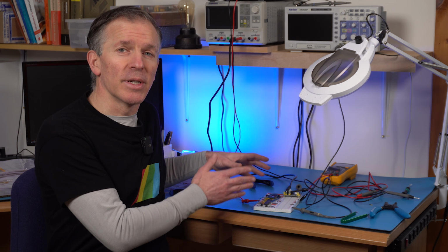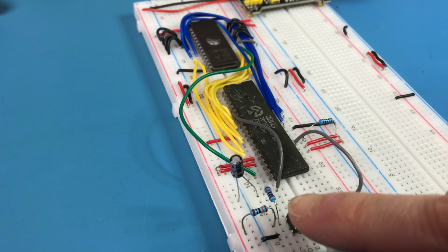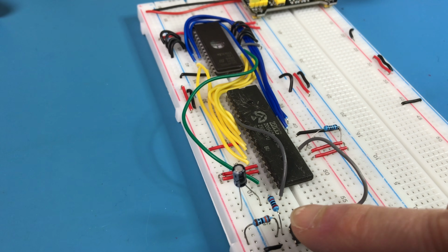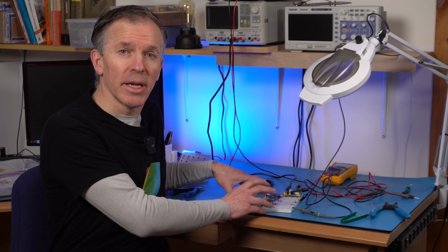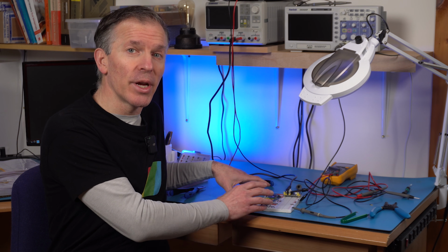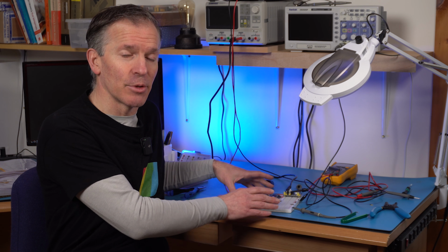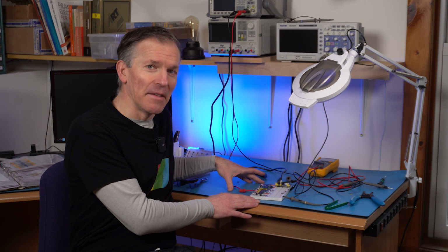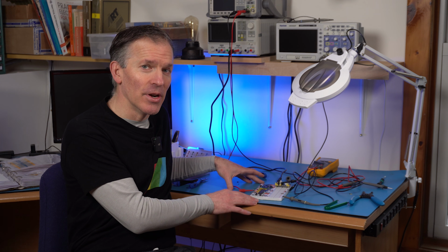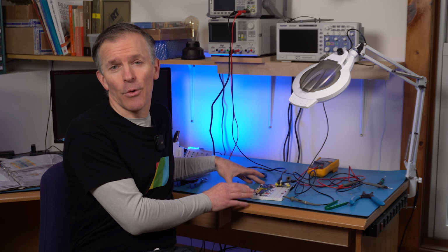The initial intention was that you would step through all the instructions with this push button, and that when we get to the OUT instruction, the IORQ signal will go low, and you could see it in an LED, and then we would examine the address bus with LEDs as well at that time. However, after banging my head for many days on this, I remembered that the original Z80 processor cannot be stepped at a really low frequency.